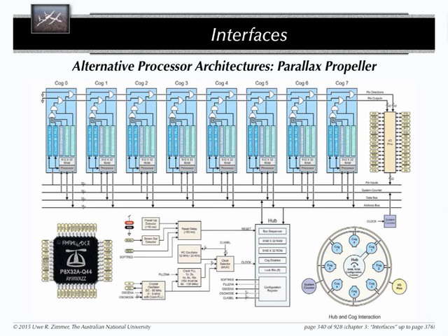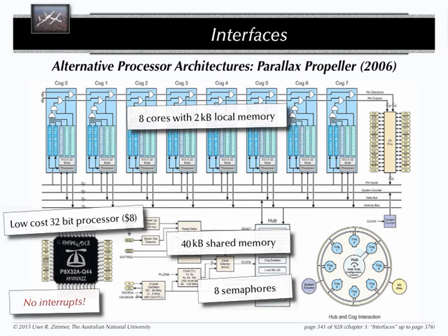If you want to actually handle a device on the outside, make one of your CPUs stare at this line. That's your interrupt controller. It's way more predictable than actually using interrupt logic and interrupting your main program in 5 different levels and 5 priorities and hierarchies. You don't need to do that. I have enough cores. Just make one of these cores stare at this line. This is my implementation of this device controller. Right? Quite a beautiful and clean design to do it like that. You have hardware semaphores on that thing. I don't think it costs $8 anymore, but it was costing $8 when I made this slide.